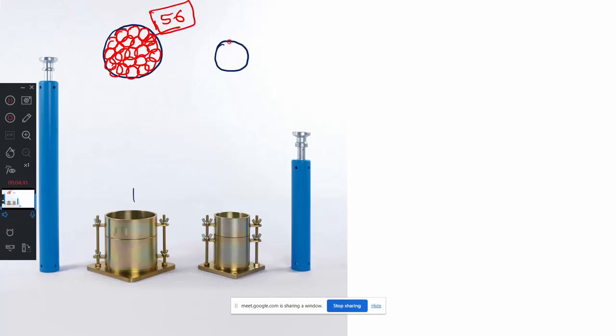Then here, this is a small mold, but you still have the 5 centimeter diameter hammer. How many blows do you give for even distribution? The answer is 25 blows. Whether you are doing CBR, light compaction or heavy compaction, that doesn't matter. 3 layers or 5 layers, that doesn't matter. It depends on the diameter of the mold.